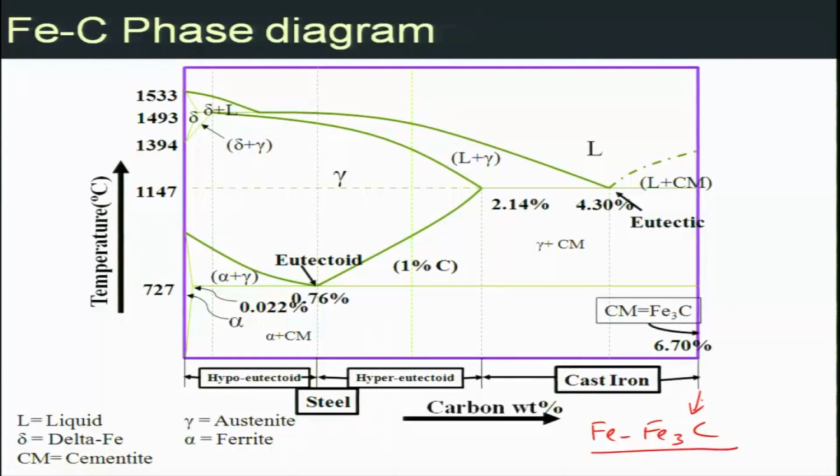Okay. So this phase diagram has multiple regions. Carbon has a different structure and different atomic radius as compared to iron. As a result, they don't have complete solubility in various forms. Carbon and iron also react to form an intermetallic compound called Fe3C. So if you have 6.7% carbon, it will make Fe3C compound. So everything will be 100% Fe3C. So what it has is three regions.